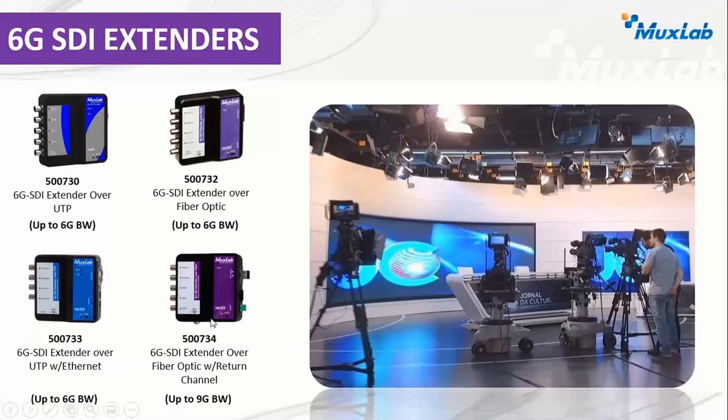And this one here is the same. You've got 4 in and a return, plus the link connection. Okay. Just one other point I want to make about all of them is they can support when you multiplex 4 signals, the 4 need to be HD SDI signals. If you have 3G SDI, we can multiplex 2 of them, and if you have 6G SDI, then it's just 1 port that can be sent over the link. The bandwidth of these devices, in fact, these 3 here is 6G maximum in total.